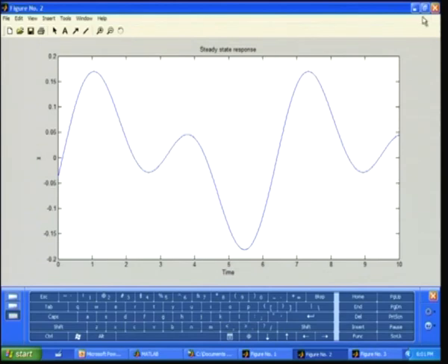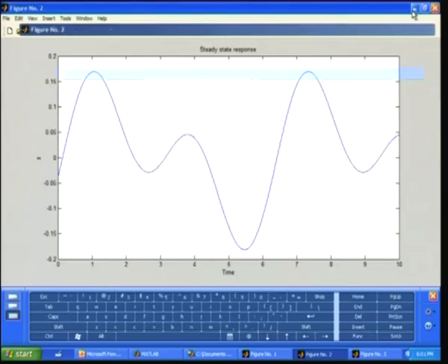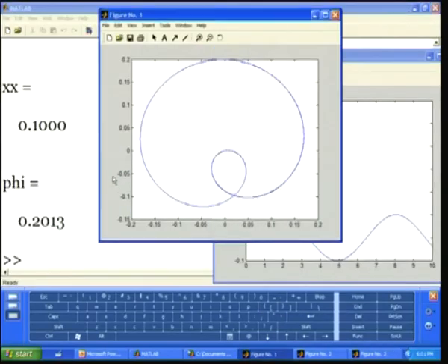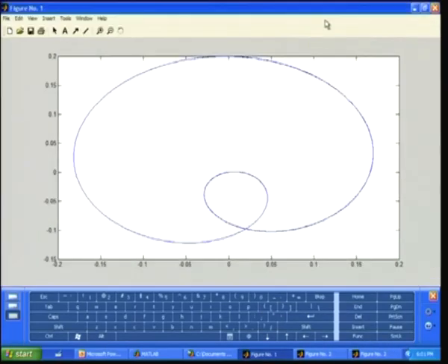This is displacement versus time, and if you plot it using a phase portrait, you plot the velocity versus displacement. You can see there is a loop here. This contains 2 frequencies of the system. As we have taken 2 external frequencies, the response shows 2 frequencies.